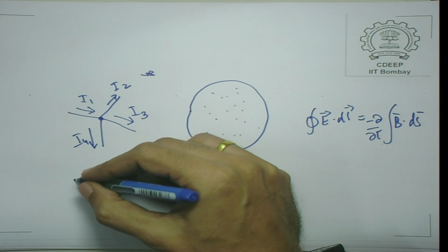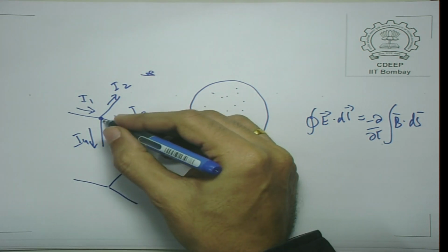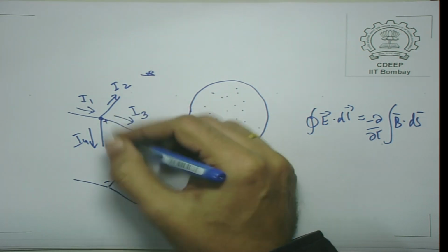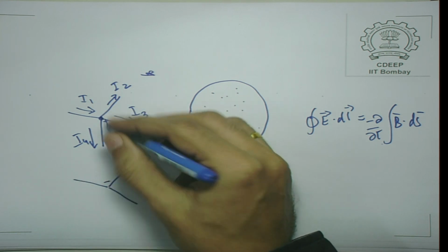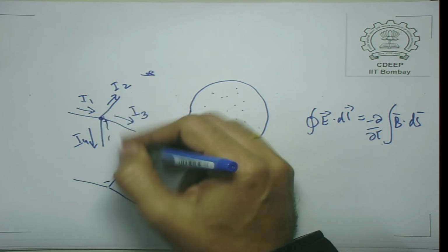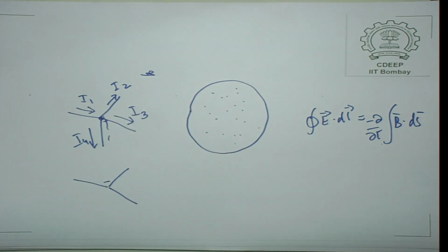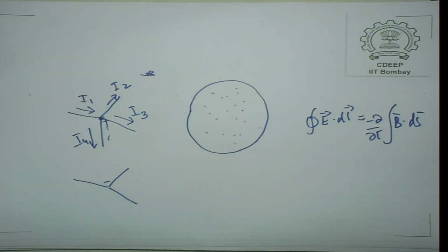In real life devices, of course, there could be a charge build up, and if there is a charge build up, there will be a kind of a capacitive effect, because there will be an electrical field drop here. So, there is what is known as a stray capacitance associated with every part of the system as well. But if the amount of charge accumulating at the node, for example here, is very small, we can neglect this capacitive effect.